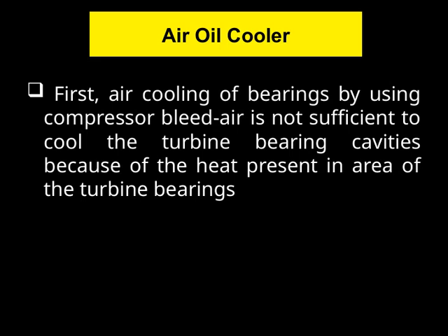First, air cooling of bearings by using compressor bleed air is not sufficient to cool the turbine bearing cavities because of the heat present in the area of the turbine bearings. As you can imagine, the temperature in this region is quite high due to the intense heat generated by the turbine operation. Simply relying on bleed air for cooling doesn't provide enough thermal protection.